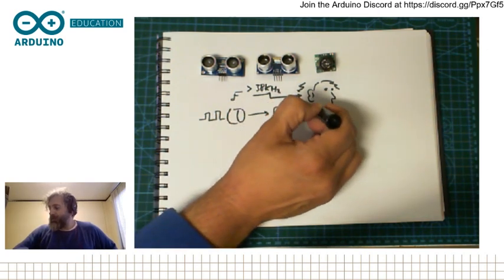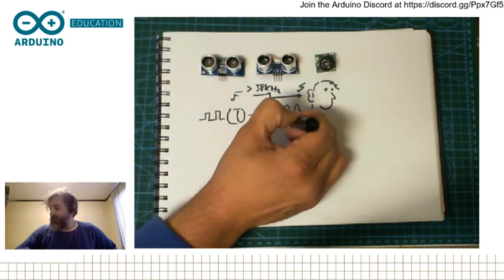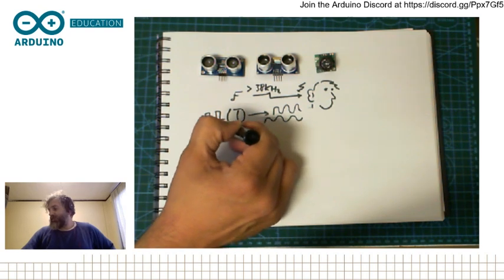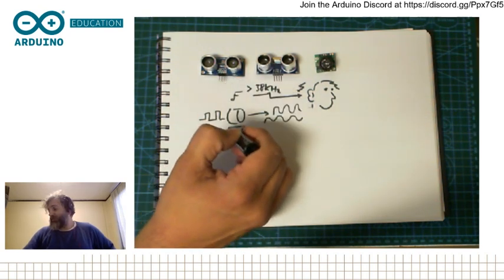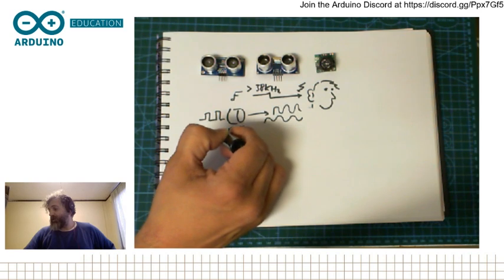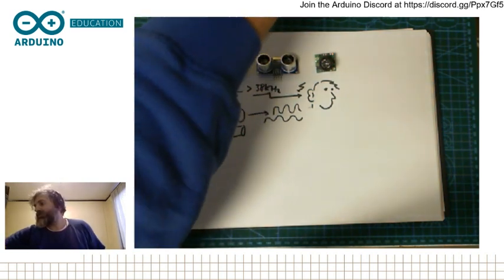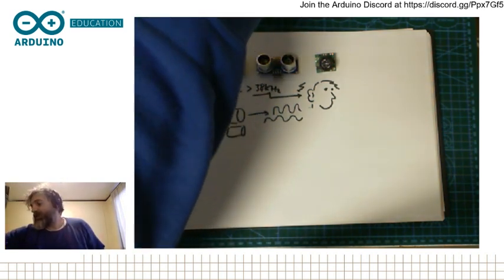This signal travels through the air, bounces on whatever object, and then travels back. And then there is a second transceiver, as you see there is 2, that takes this one and translates the answer into a pulse that tells us for how long the signal was flying. I'm going to take a pen just to signalize one thing.